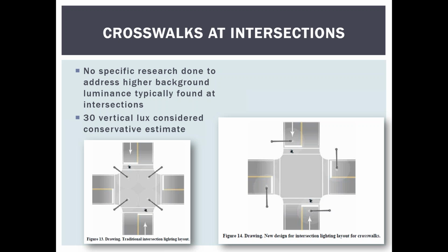And I heard Kay Fitzpatrick, who's doing the research, saying that there is a sweet spot for the amount of light level, and the amount of light at night should possibly be less than the amount of light provided during the daytime, because during the daytime you're fighting with the sunlight, especially in the desert Southwest, where 75% of our days are sunny. Compared to nighttime, that light could be so strong it could be more distracting, and make it more difficult to see the pedestrian.